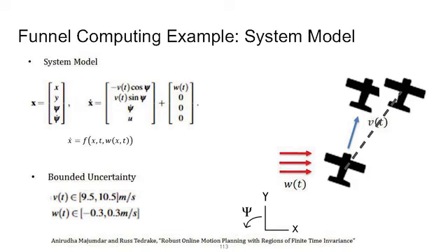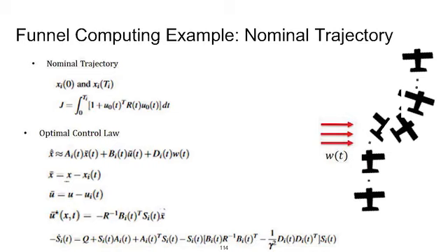So how do you deal with that? Well, you start with your nominal trajectory that has the plane flying perfectly straight. There's no uncertainty, everything is deterministic, and it acts like you want it to. So right there, the wind hits it. What do you do? You have to have some kind of controller to bring you back to your nominal trajectory and try to control you around the system.